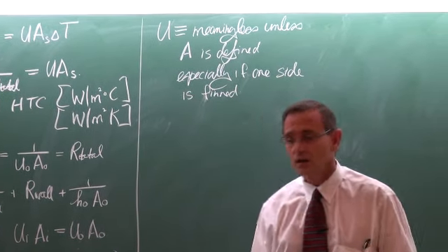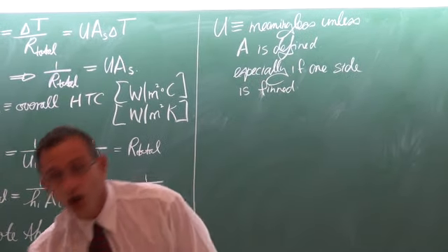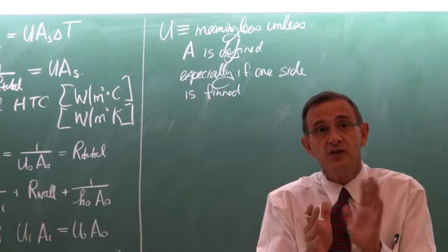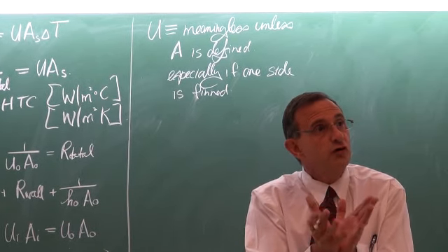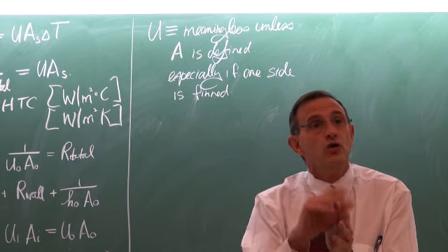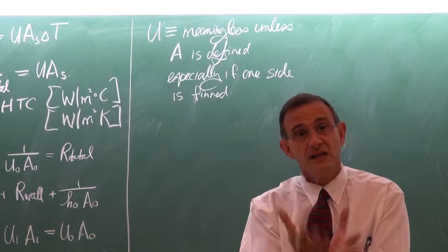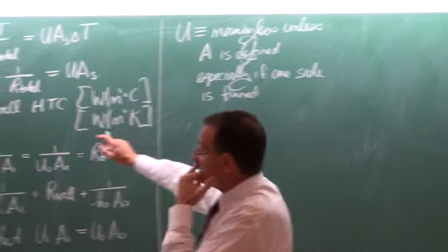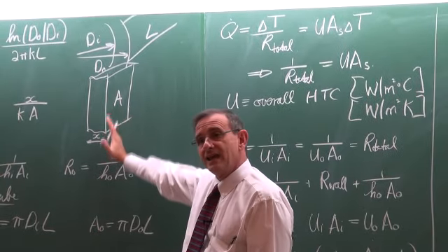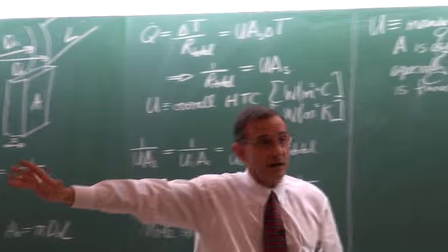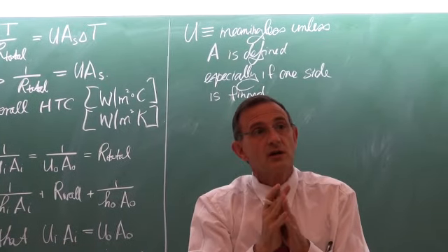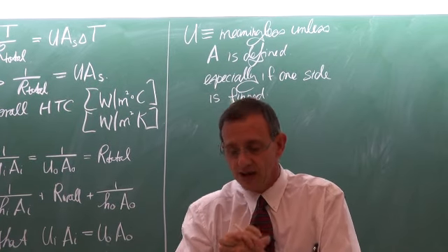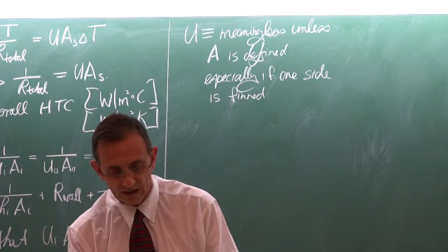Okay, in the previous lecture, I hope you remember, I told you that normally when we've got a heat exchanger and one of the two fluid streams is a gas, then on the gas side we will always have fins. So especially if we have fins, this area on the outside, the finned area, is going to be much larger than the other area. And then the two heat transfer coefficients can differ dramatically, and I'm going to show you an example in that regard.